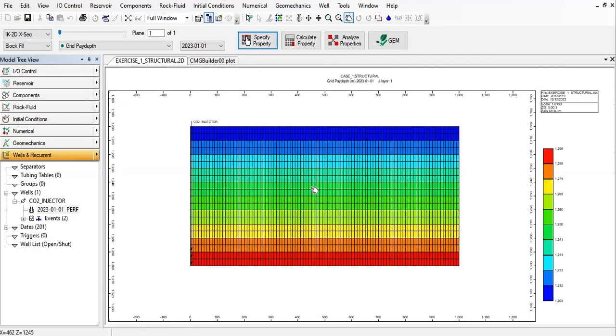The important thing to note is that because it is a two-dimensional model and it is the migration and trapping of CO2 that is of interest, the injector is to be shut in after 1 year of injection. You need to know the basics of CO2 sequestration. CO2 injection is not forever. Maybe you will inject for 1 year, or 10, 15, 20 years, but after you complete the period of injection, you will shut your well in, and then you just monitor using seismic, logging, and others.